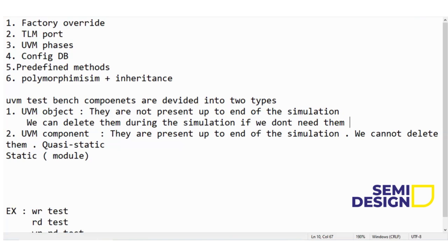So can we say that driver and monitor are running parallelly? Because you said that scoreboard is consuming 0 simulation time. See, this 0 simulation time, when I go to the fetch concept, you will come to know. Normally in the scoreboard, we do the checking part. We don't write any time-consuming things there. But yes, if you are saying that I will give some delay, #1, #2, #3, yes, you can give it. But mainly driver and monitor, you just see, the driver will be sending some signals. Definitely there will be some timeline, pos edge of clock, neg edge of clock, those things.